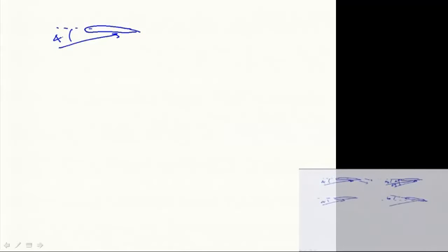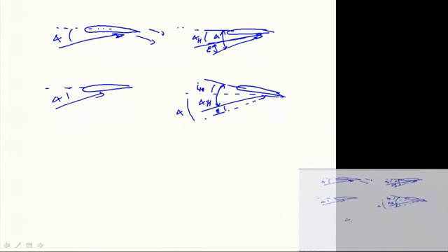And then we have the angle of attack, alpha H. We have it now increased, and because we have lost a part of the epsilon part compared to the original alpha. So from this figure, you can see this should be the angle of attack of H. It's a bit difficult to write all the small indices on here. From this, we can see that if you want to calculate the angle of attack at the horizontal surface, you take the original angle of attack, we subtract the downwash, and we add the trim setting of the horizontal surface.